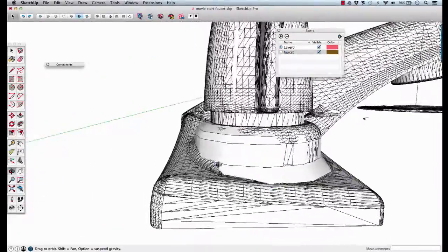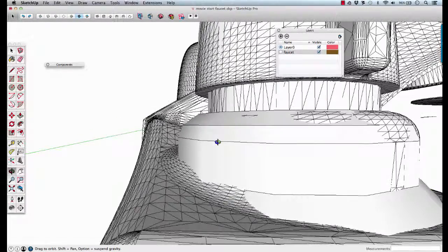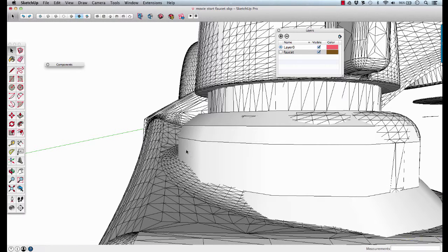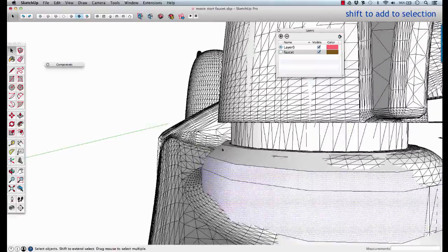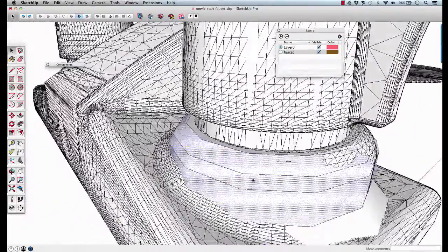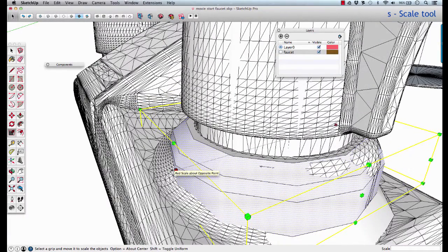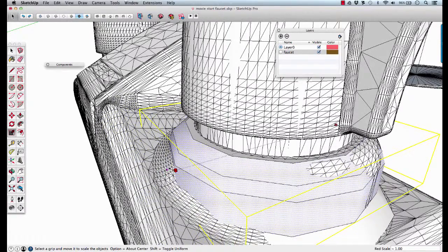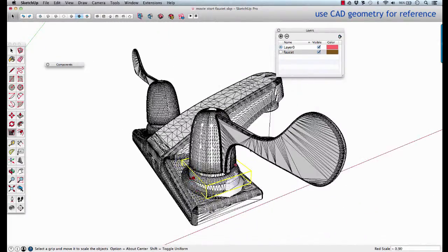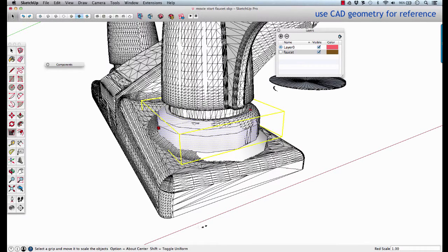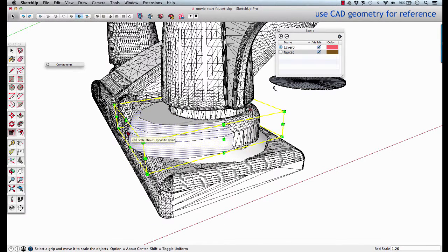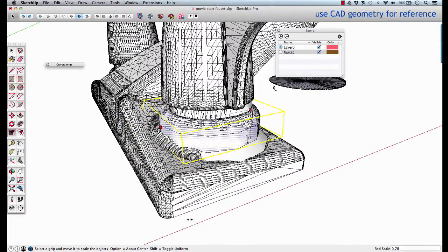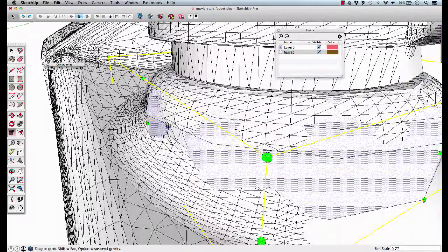So now we want to correct the back side and have it match the CAD better. Select that smooth surface. Actually, we'll select all 3 of them, and we want to move them back, or scale, S. And this time we're going to go from a side grip, and instead of doing it by the center, we're just going to move it till we see it start to match. I'm going to zoom out, till we see it start to match the CAD. So let's try it again. Click on it, gives us a little better definition, and click when we're matching the CAD.